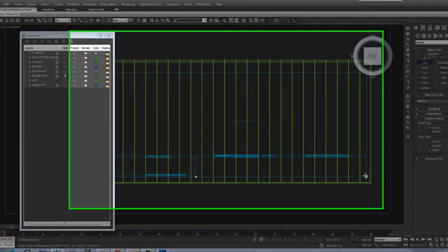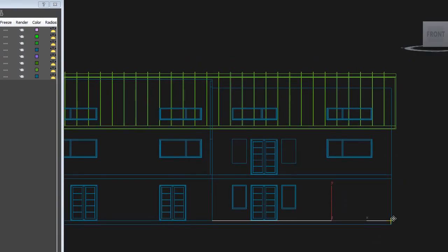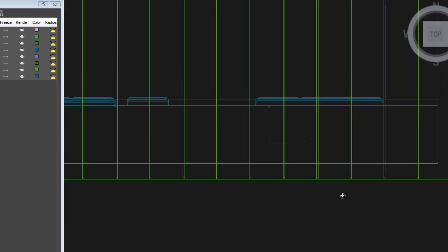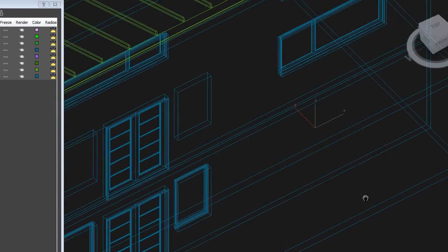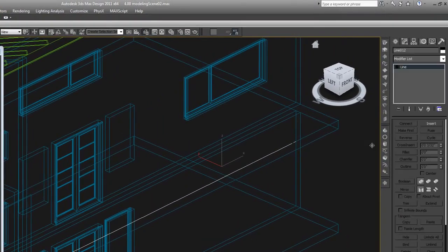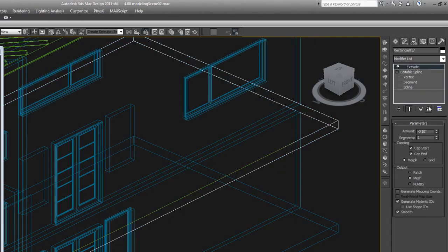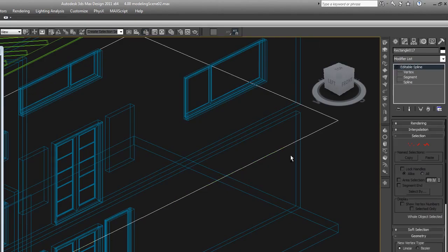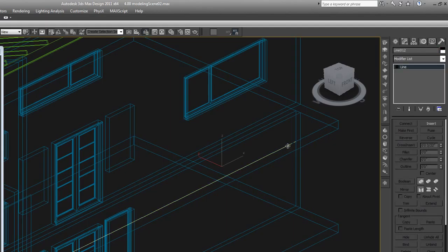Railing used to be so hard for me until I figured out a few of these tricks, and then it became, as you saw, really easy. So let's make it more of a railing type thing instead of pieces of glass. We'll say this is mounted on the floor here instead of on the face. So if we select this, nope, that's not what I wanted. Okay, let's get that line, the right line. It's that one.